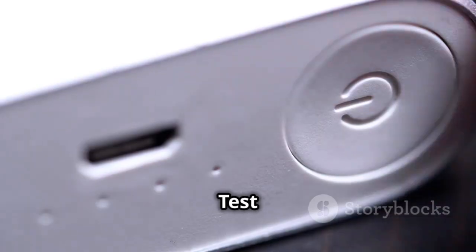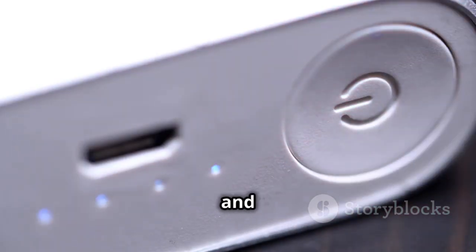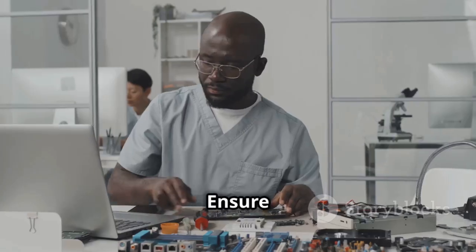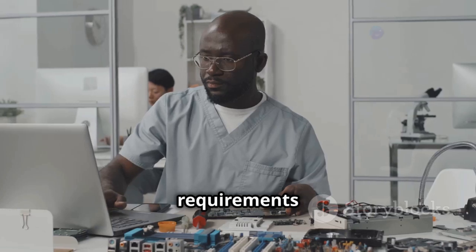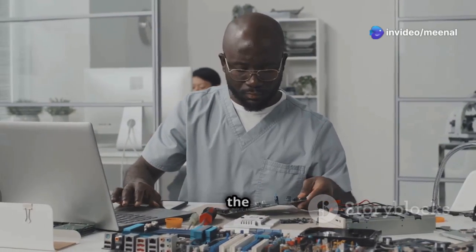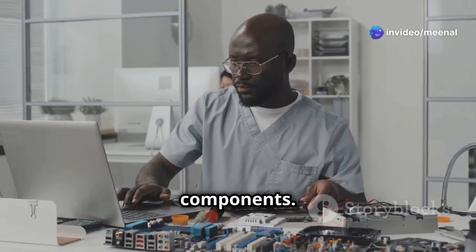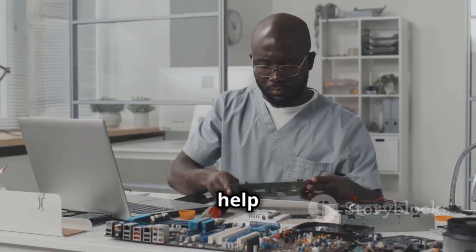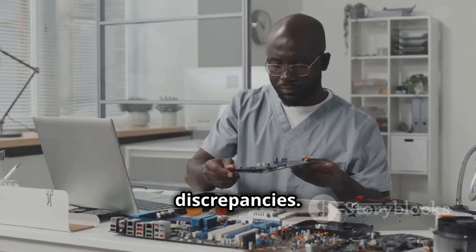The manual reset test. Press the manual reset button and observe the reset signal. This test simulates a manual intervention and helps verify that the reset circuitry responds correctly to user input. Ensure the reset signal behaves consistently each time the button is pressed. Ensure the reset signal duration meets the requirements specified in the datasheets. Datasheets provide crucial information about the expected behavior of components. Cross-referencing your observations with the datasheet specifications can help identify any discrepancies.